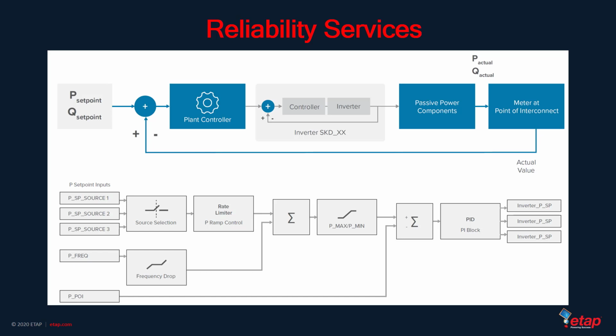This is accomplished by balancing two modes of operation: active power control and automatic voltage regulation. Coordination between generator owners and system planners is crucial to a balanced grid. It is important to regulate the allowable amount of power at the point of interconnection. Active power control limits generation at the point of interconnection to predetermined set points. This purposeful limitation is called curtailment. Grid support through automatic voltage regulation is done by regulating reactive power.